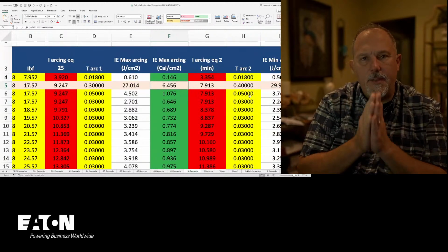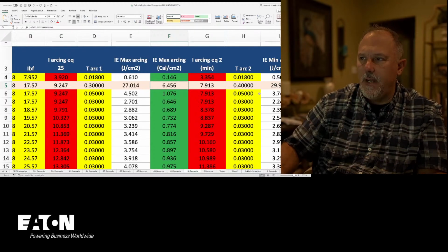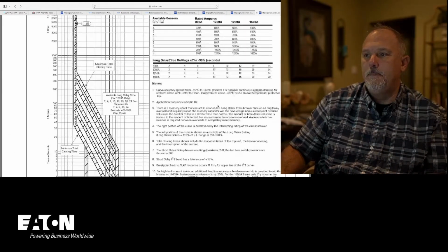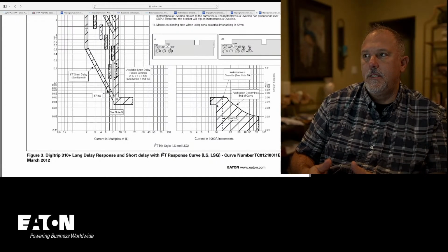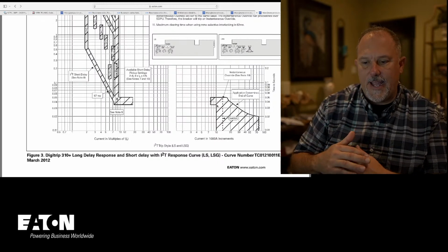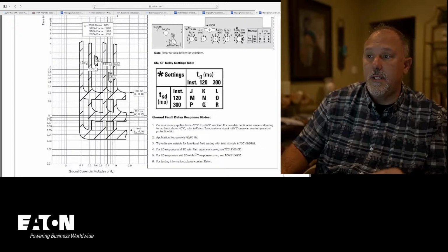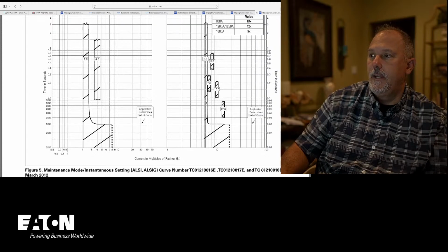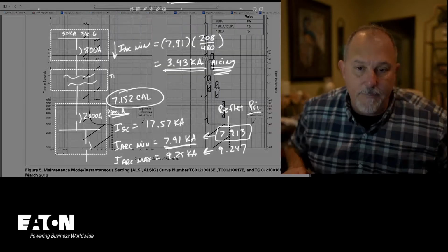So depending upon the overcurrent devices that you pick, you'll probably spend more money for that specific device because it has more functionality. That's the challenge. You can add some flexibility and get a short time delay that has a fast acting and get your better clearing times, but you have to strategically pick the right overcurrent protective devices for the job. I would love to have a 0.03 clearing time, and that would be the best bet.